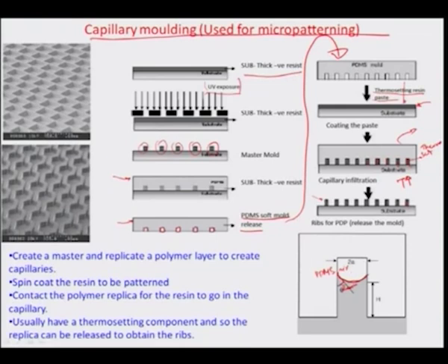And so, if there is a contact angle which is formed in these capillaries, you can safely estimate that the capillary will not be totally filled, and there would always be a gap in the capillary end when this resin occupies a portion of the capillary, and this can be a reason for inaccuracy of these pillars when you talk about many such pillars and arrays of pillars.